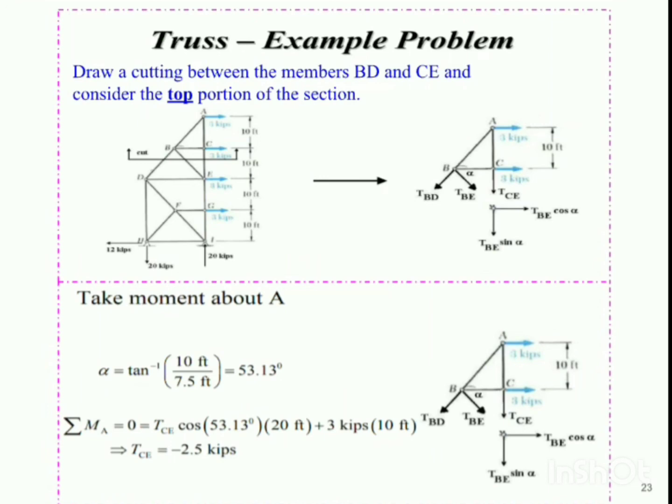But again I'm repeating that we shouldn't change the direction of the forces that we have shown in the free body diagram. We need to keep them as they are. We need to carry the negative sign with these member forces ahead if required in the equation.